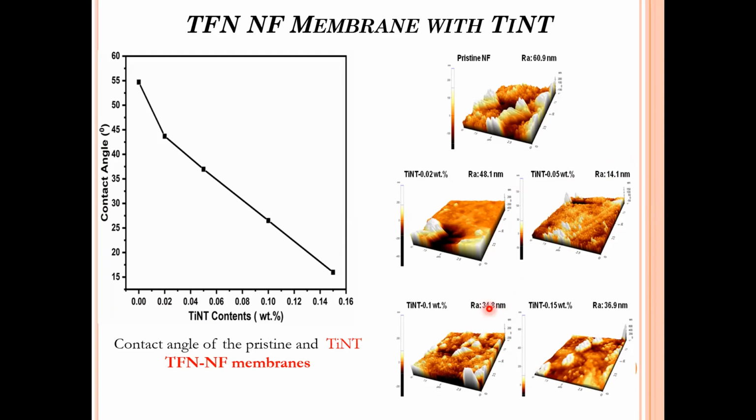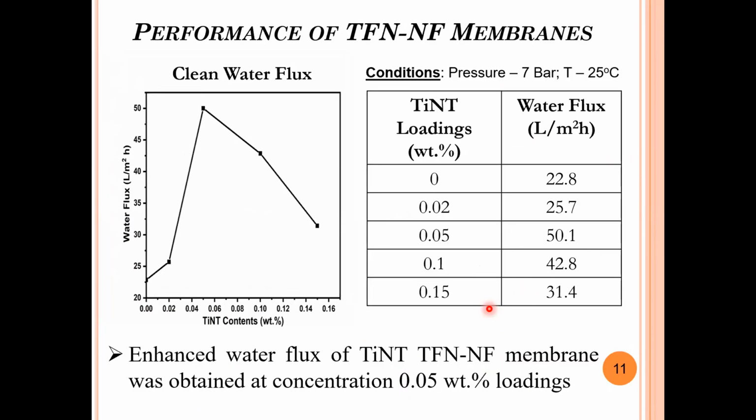So it is our best judgment to select which membrane we want based on the flux we can attain here. For this particular nanofiltration membrane, we applied a pressure of 7 bar and conducted the test at 25 degrees centigrade. The skid also has a chiller, which can vary the temperature, and you can find out the effect of temperature on the clean water flux through the membrane.